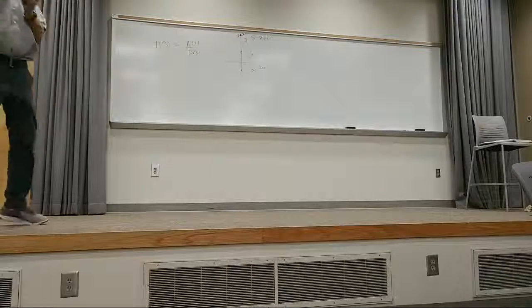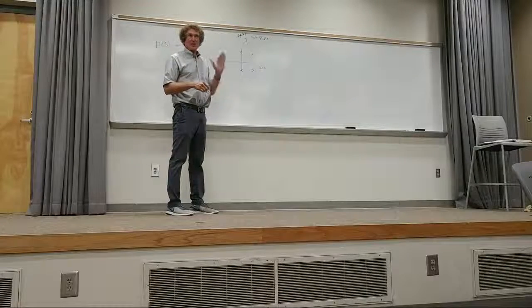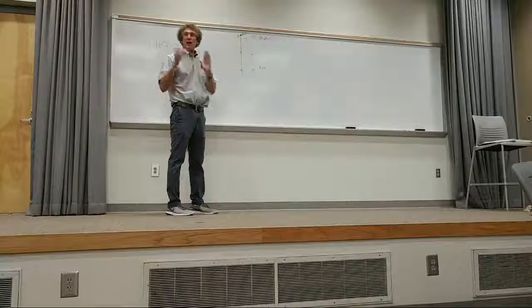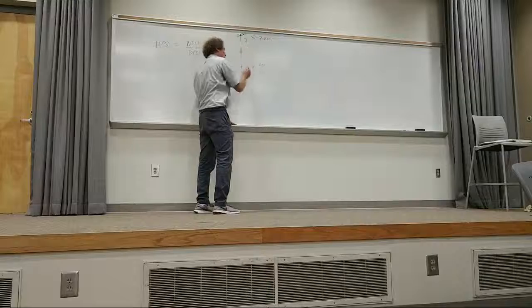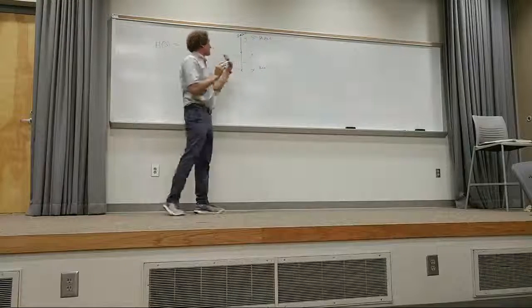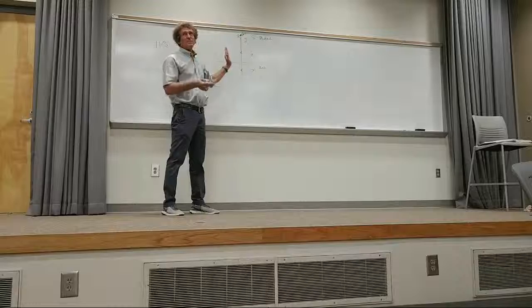So even though the poles could be the same for these networks, and I'm not going to spend much time on this, it comes later, it depends on the configuration whether or not they're destructive. It determines whether it's stable or not. However, any pole in any part of the right-hand plane, which is everything to the right of the j-axis, will be unstable, and whatever system you've got is going to go into failure. Failure means so many different things.